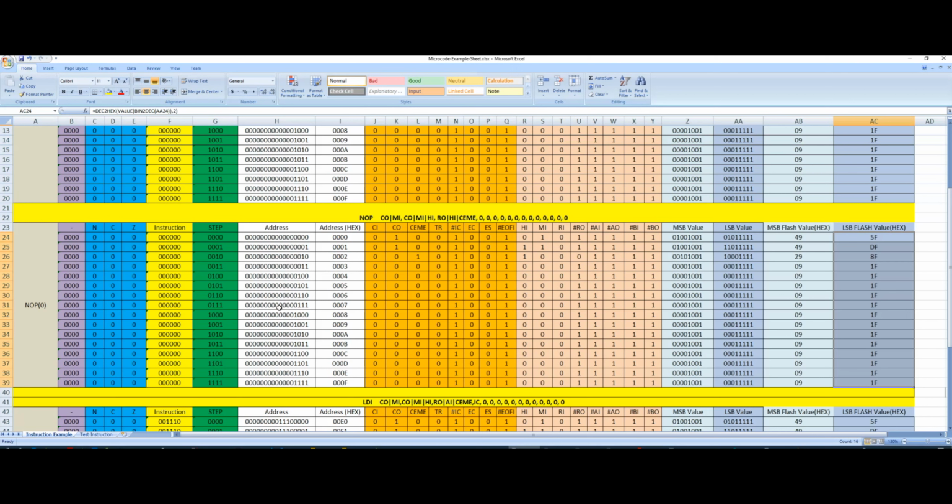However, in this example, as you can see, I set all the flag values to 0. In the final version of the microcode, you actually have to come up with all combinations that these flags could have and repeat exactly the same instruction 8 different times.